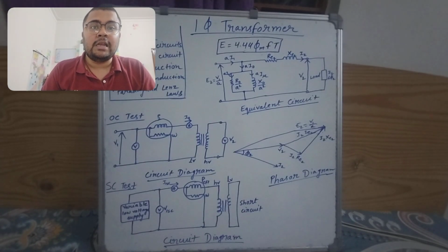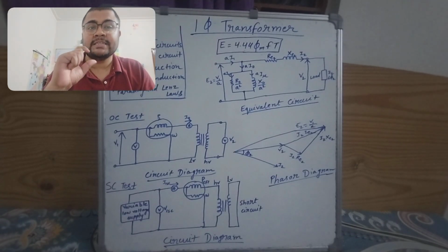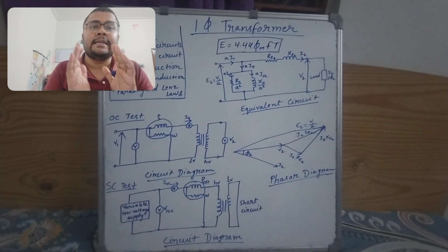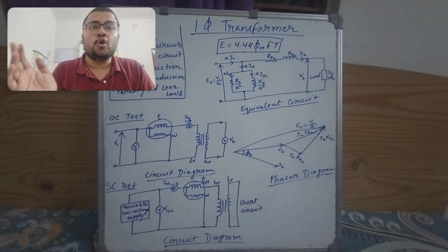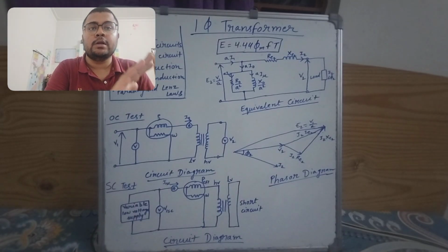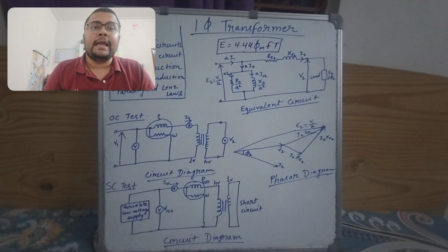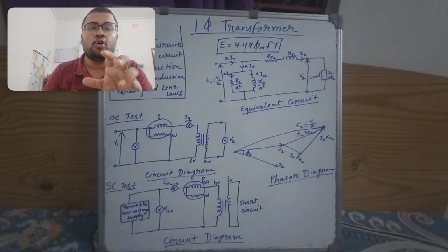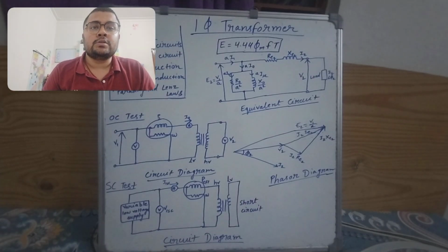So this was all about the single phase transformer. There is one more thing, which is known as voltage regulation. Voltage regulation is basically the difference between the no load secondary voltage and the full load secondary voltage. And when we need it per unit, we just divide it by the no load secondary voltage. That is a different topic.